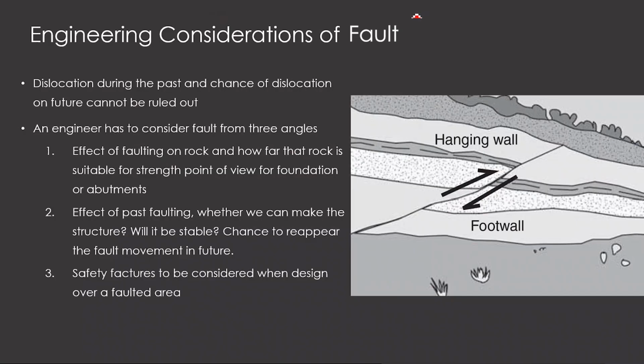Okay, so as a civil engineer, what are these faults which are going to affect us in construction activities? When I am talking about faulting, on the surface you may not be able to see it, but in the subsurface there are changes in the rock. For example, the rock layer on which you are expecting to do the foundation is at a depth of 10 meter here, and in this area it is at a depth of 8 meter, so there is a displacement. These are the kind of things you are expecting from faulting. There is an effective displacement or dislocation of the layers below the surface.